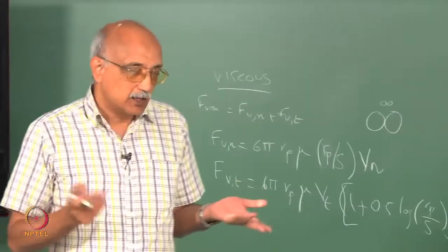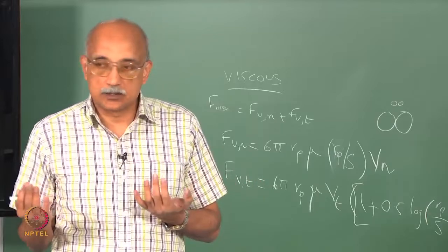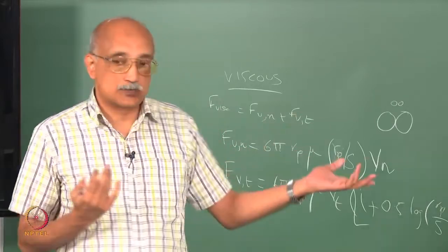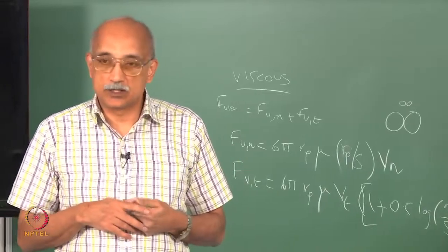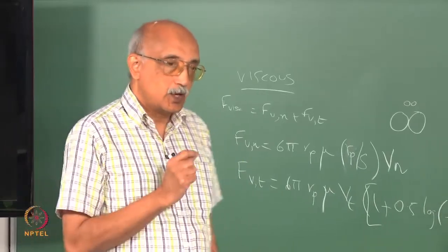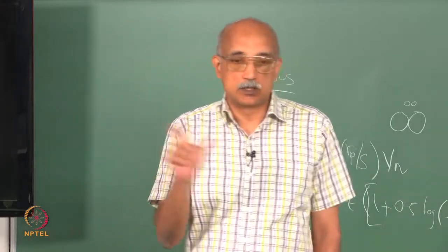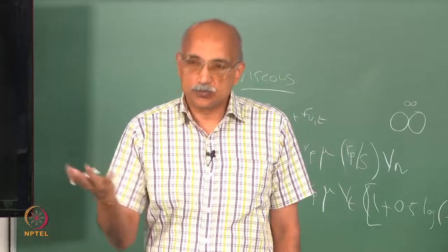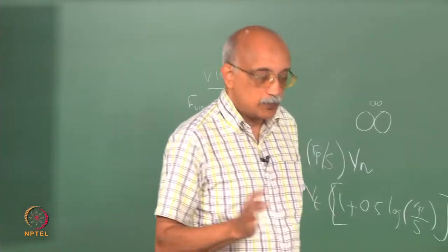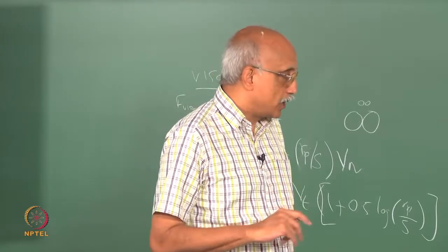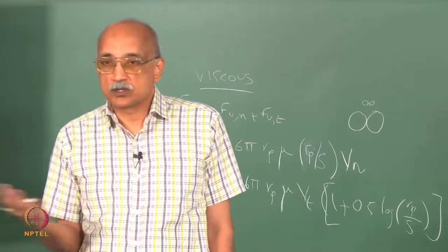Alright, so the point is there are many different cohesive forces: van der Waals, electrostatic, capillary forces, viscous forces, spring like forces, even the hydrophobic, hydrophilic forces that we described earlier. As we saw, these are very important in deciding whether two particles in suspension want to adhere to each other or repel each other. Two hydrophobic particles in a hydrophilic medium will tend to attract and so on. So, the hydrophobic slash hydrophilic forces are also important, and of course, if they are magnetic particles, then magnetic forces will become important and so on.